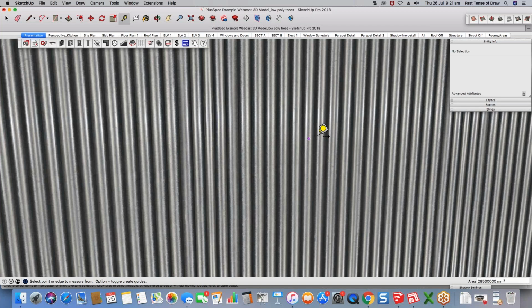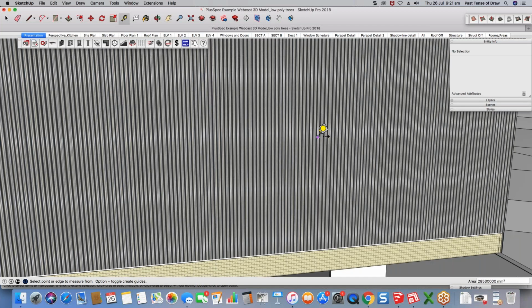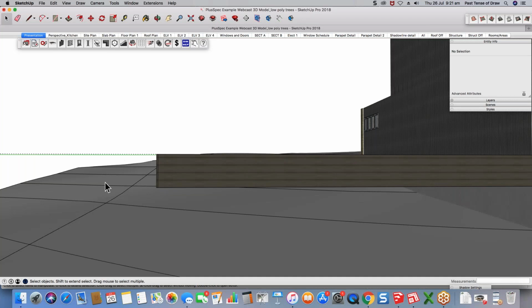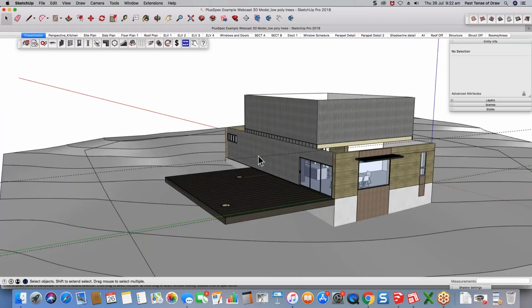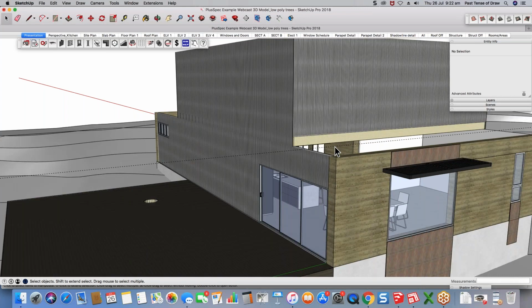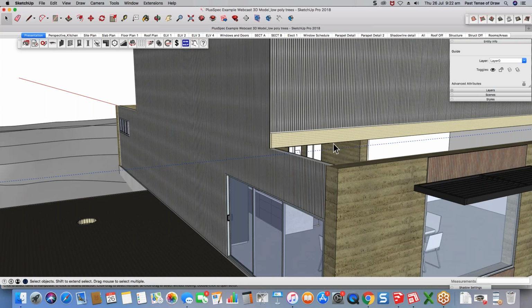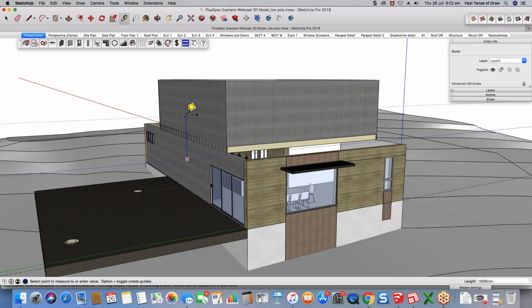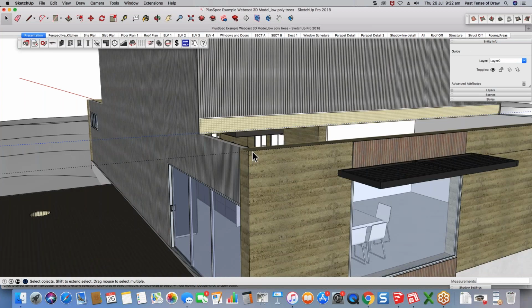So if I go on an elevation, you can now see that I've got my ground level, and then I've got my finished floor level on the 2nd story. I could even go further to this. This might be structural level, or maybe I even want to capture different parts. So if I really wanted to, I could start again just copying the grid and even go to the underside of my walls for my ceiling level. For example, if my ceiling level was going to be at the top of that wall. So really, really simple tool, right?